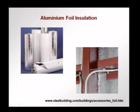These are some rolls of aluminum foil insulation. You can see the shiny aluminum surface in cases where the aluminum is on both sides. Sometimes aluminum is only on one side because the other surface is not exposed. This is a case of an application in a partition where we can see the aluminum foil on the top. So, this could be the interior of the partition. There might be another layer of material on the outside, and on the inside we will have the aluminum based insulation to cut heat transfer through the partition.